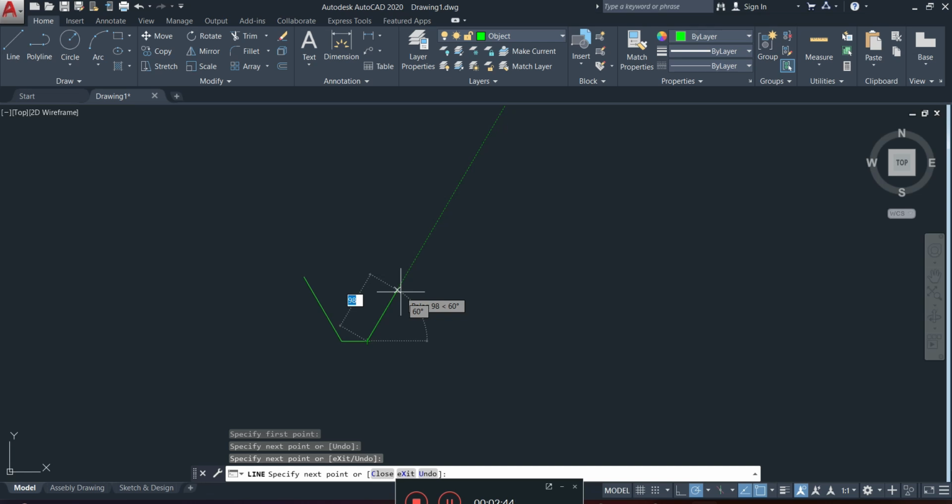However, there is a downside to this. It might seem good and nothing is wrong with it, but if you're rushing things, it's easy to get messed up. I always say, once you see a green line, it means you're safe and you can go ahead and click. But in some cases, you might shift your cursor accidentally, as you see there's no green line now, and you didn't realize, and you accidentally click. Instead of that line being 30 degrees, it is now something else. Then at the end of the drawing, you realize that something is off. Why aren't they touching? Why is this over there? It's because of a reason like that.